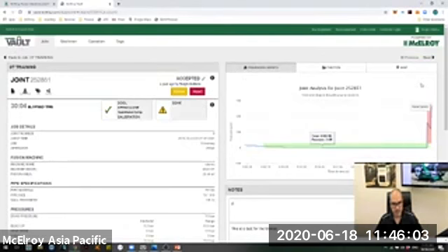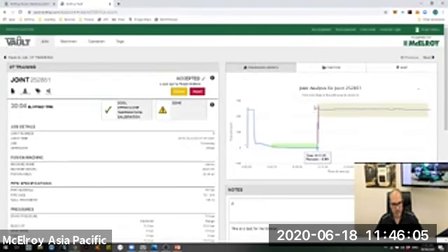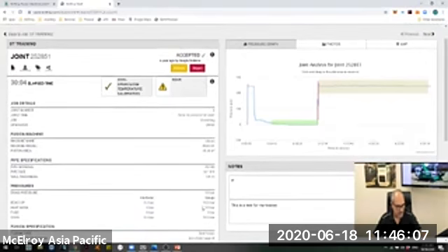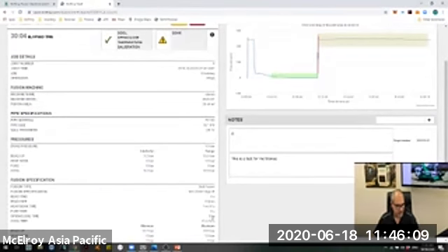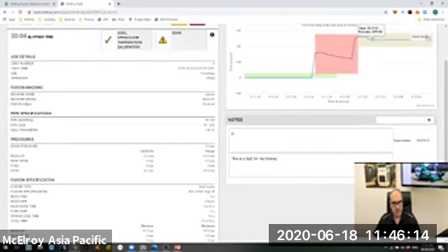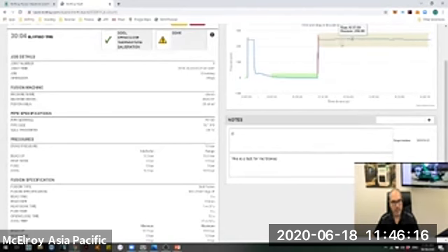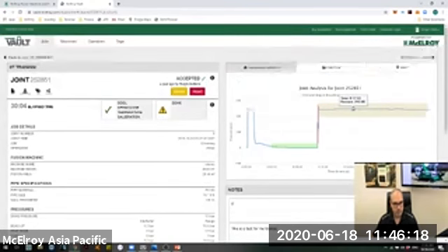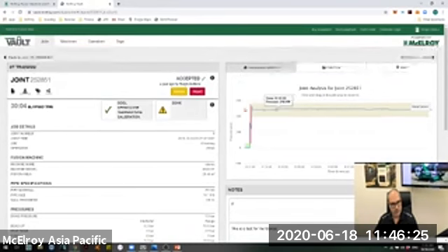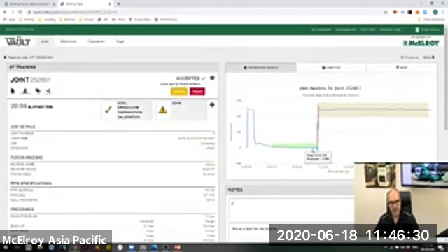Also, we have the open and close time, which in this case is 12 seconds. So basically, we need to open the machine, take out the heater, and close the machine again within 12 seconds. And there's another window that specifies the cooling time, or the time that the pipe has to be on pressure during the welding time.